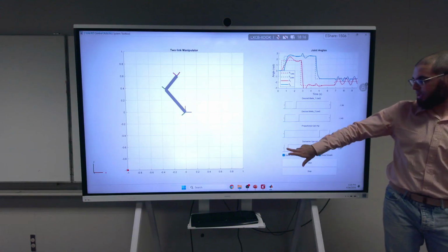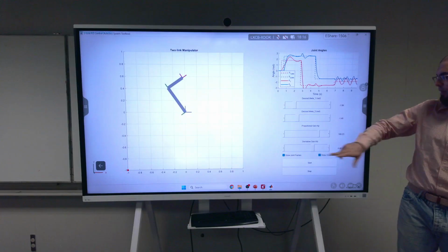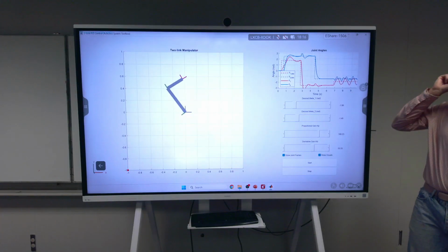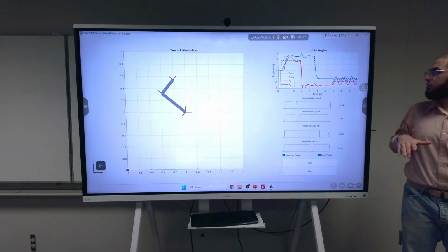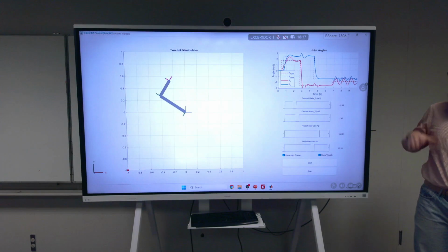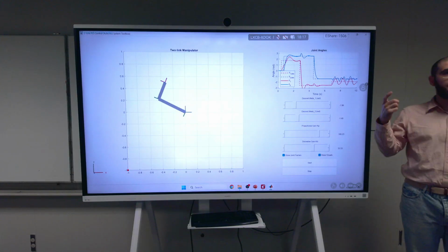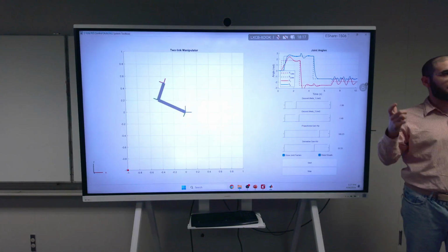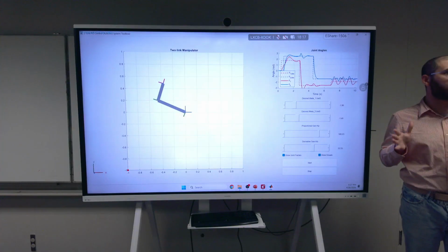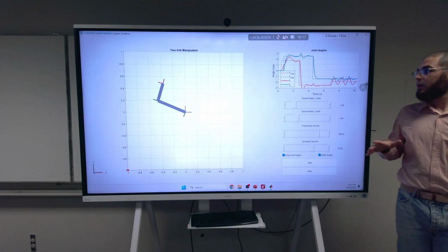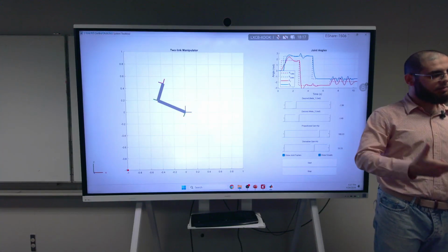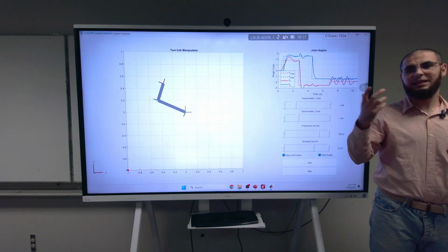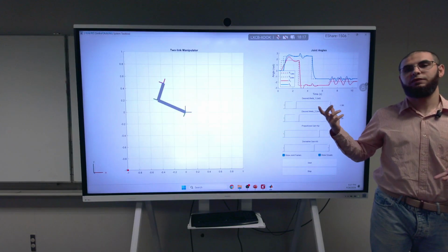Now we choose the gains. So let's pump it up immediately. You'll find that it should stabilize at the value that we chose. You see the whole idea of actually deriving this, I hope you got out of the course, is that one of the key things about thinking of the PD controller as something related to stiffness and damping is that it makes your life tuning this stuff very easy.